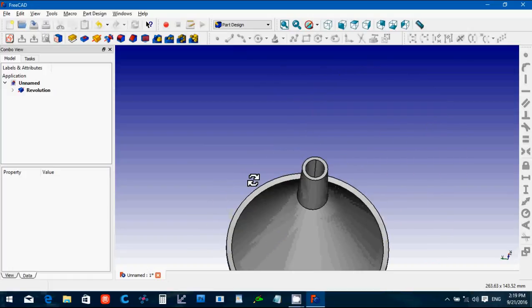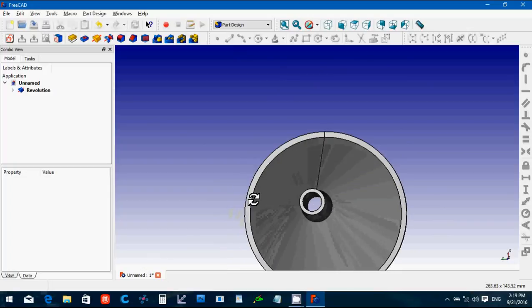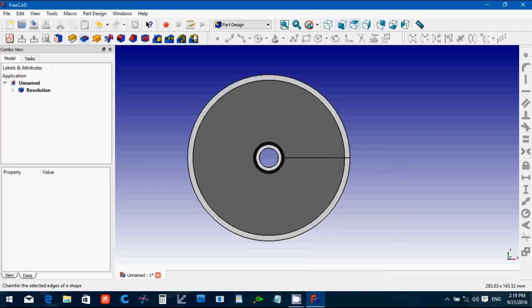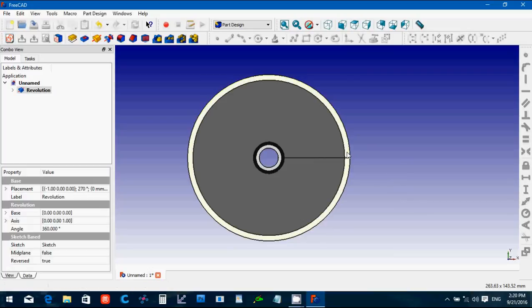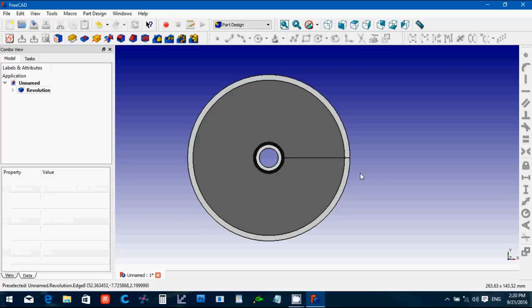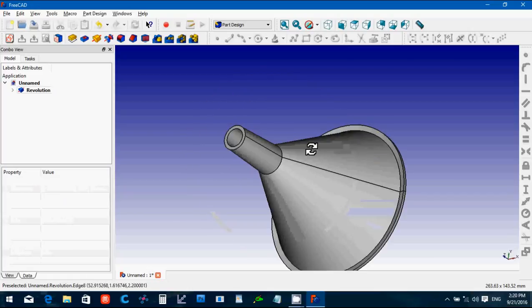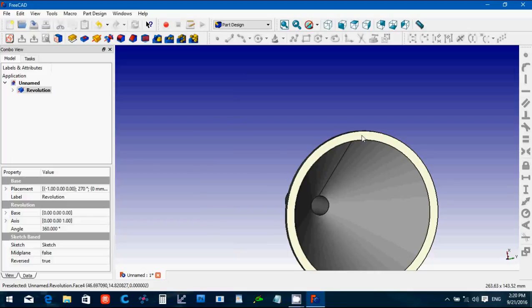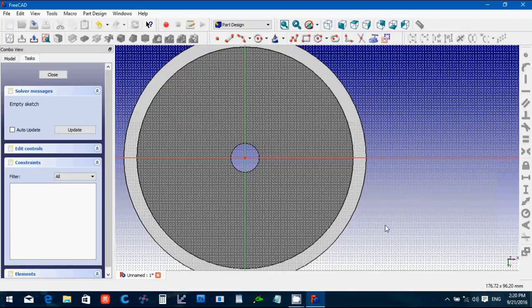As a finishing touch, let's put the hook part on. So look from the top, click the surface here of the ridge, create a new sketch. That looks like a planar sketch to me. Let's see, maybe the bottom one. Okay, I guess I've got to go from the bottom.